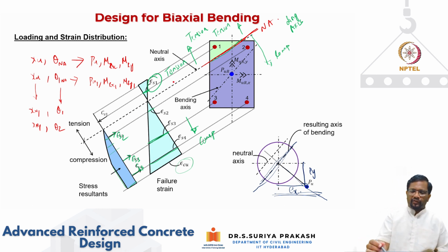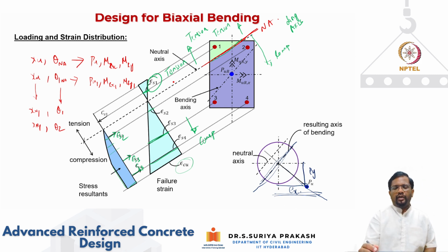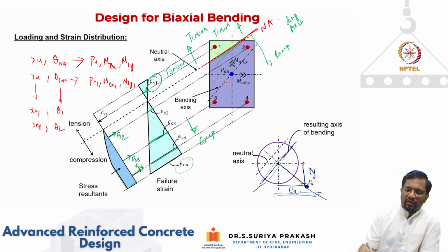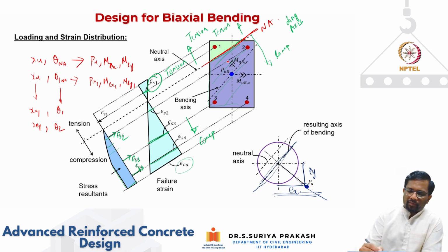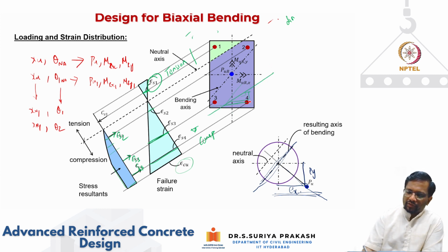In this case, for the neutral axis angle and depth that we have found, you are having this kind of five-sided area. You can have a triangular area depending upon where your neutral axis depth is. For example, if I have the neutral axis depth at this location, then this will be in compression, and this will be the triangular area.